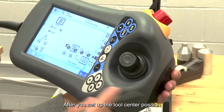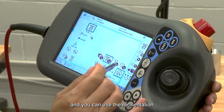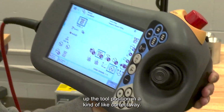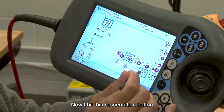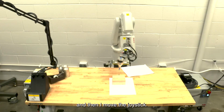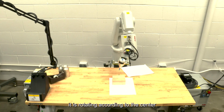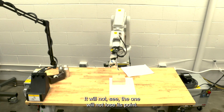After you set up the tool center position, you can use the reorientation of the tool to check whether you set up the tool position correctly. Now I hit this reorientation button, and then I move the joystick. You can see the robot is rotating according to the center you just defined over there. It will not lose the point.